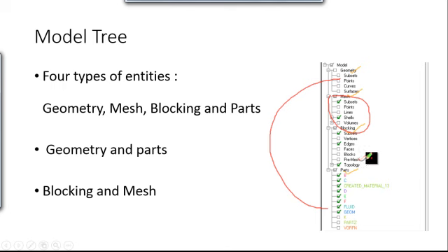So you will also get those options over there. For some in-house solvers, you also need to have the structured mesh. So just right click on the pre-mesh and you will get the option for the conversion to the structured mesh easily.